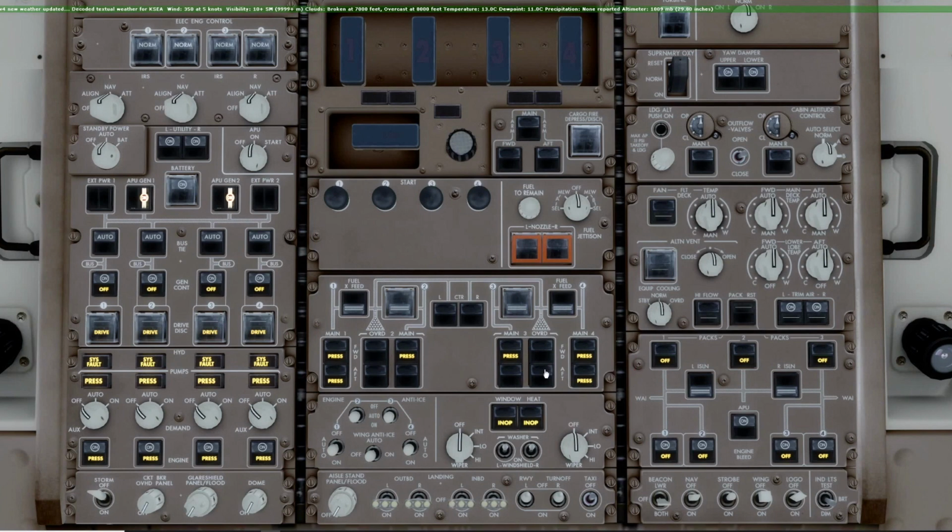No pressure lights in the overrides in the center tank. And if the APU is running, no pressure light in tank 2 and 3 aft, since the APU is using that pump. Engine anti-ice is auto, wing anti-ice is auto, windshield wiper switches are off, turn on the window heat. That should get rid of those status messages.